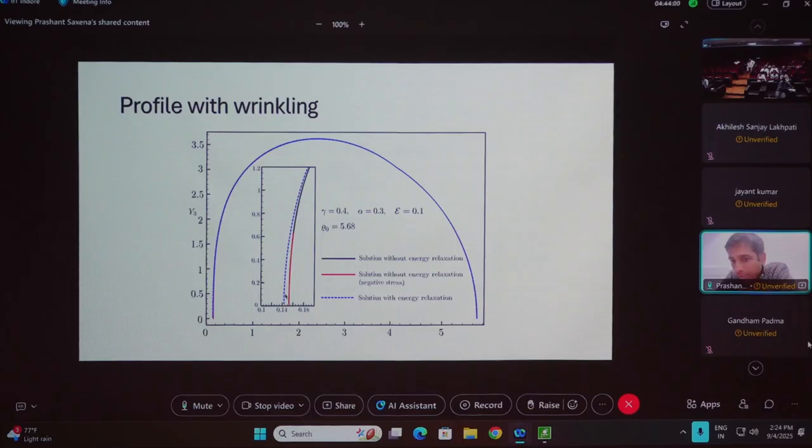Okay, so it's hard to see, but now you can actually predict that this is the zone in which wrinkles will start to appear. This is the area where stress is going to be 0 or negative, and if I keep on inflating, the inner wall of the membrane will start getting wrinkles in a certain direction. So this is the way to predict the wrinkling instability in the membrane.